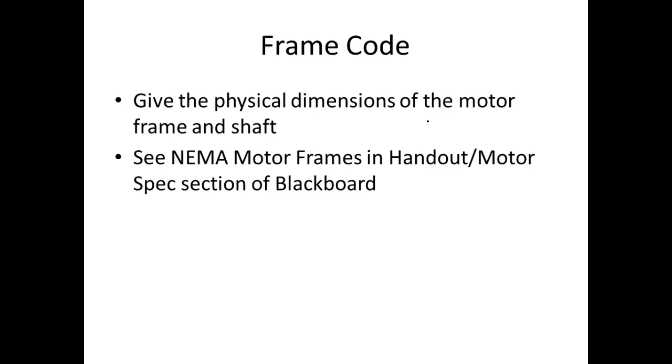One of the things they took upon themselves is to set up NEMA frame numbers. Most of your motors now are going to have a frame number on them, which tells you how it mounts, the spacing between the mounts, the length of the shafts, the size of everything, specified in one letter, and you would look that up on a chart.